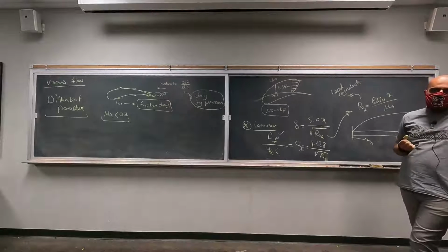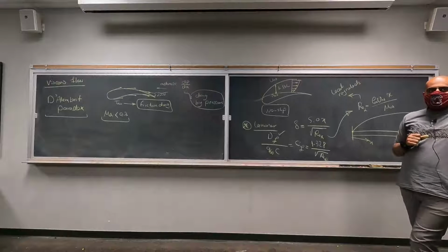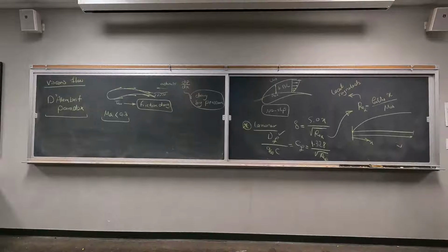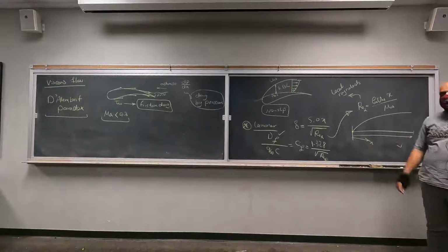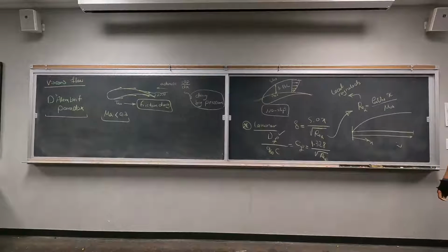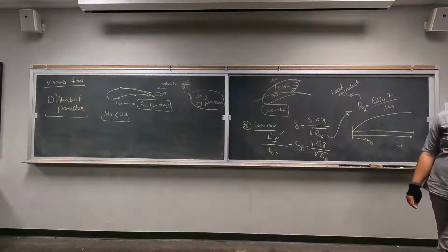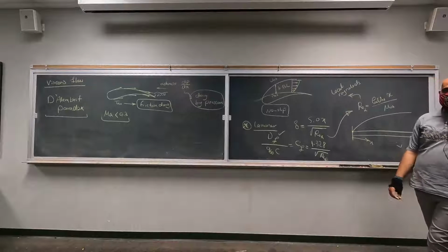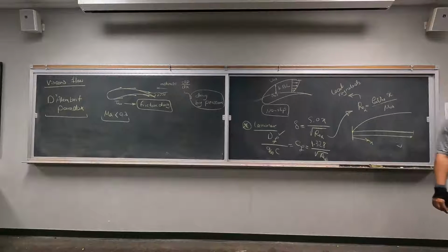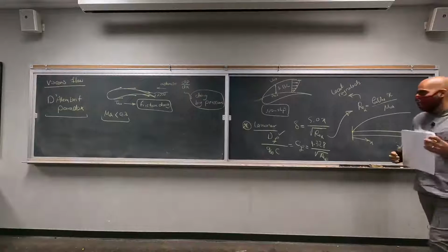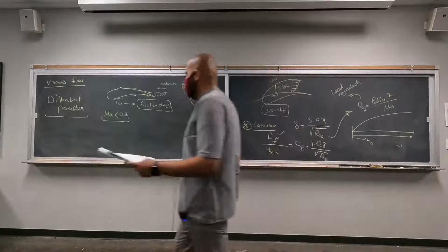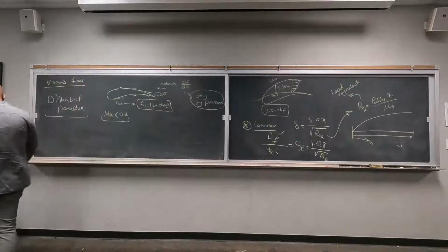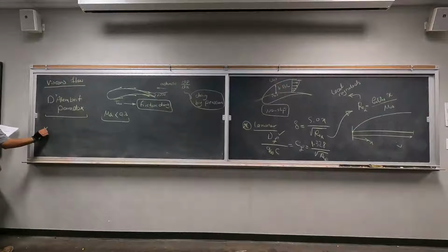So we use the Reynolds number to determine whether the flow is laminar or turbulent, right? So what will happen to our calculation here if the Reynolds number is high enough that we can get turbulent flow? Can we use these formulas? Obviously, no, because these formulas are derived for laminar flow, which means that we have to have another set of formulas for turbulent flow.